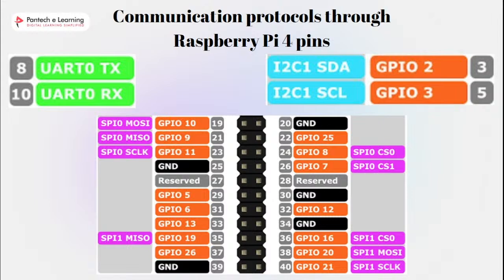Each slave has a unique ID, so the Raspberry Pi knows which component it should talk to. For using I2C, you will need 3 pins. One is the ground pin. I guess you start to get used to that, right? And another one is the clock pin.